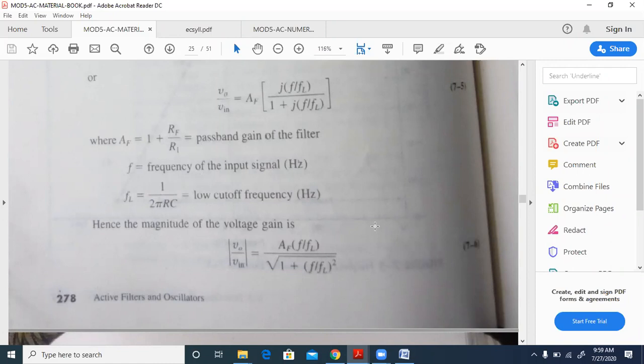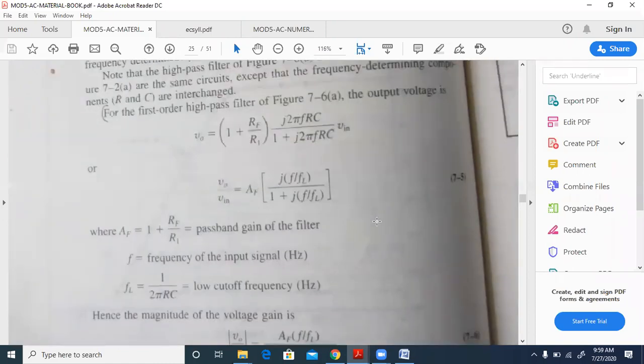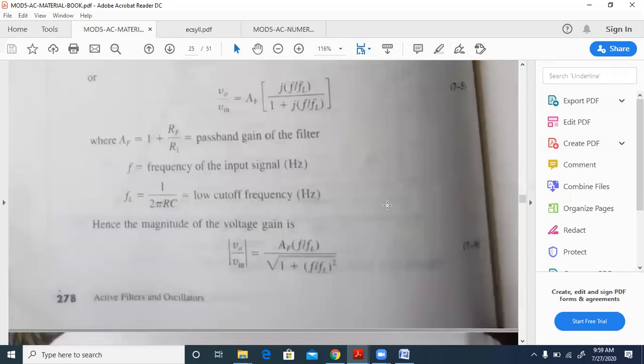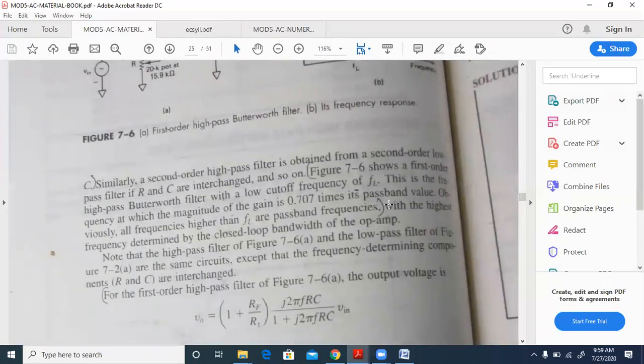Okay. So then we need to just find out the value of R and C. You need to write there RF equal to 0 and R1 equal to infinity. You can write, or at least you write, voltage follower. We'll use a voltage follower. R and C are to be found. The formula is the same. FL is equal to, now we are talking about high pass, you write FL is equal to 1 by 2 pi RC. Choose the value of C and calculate the value of R.